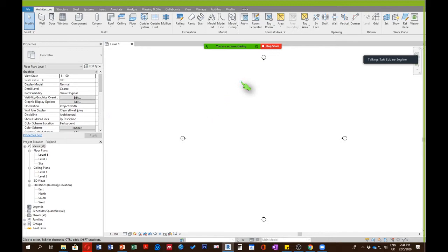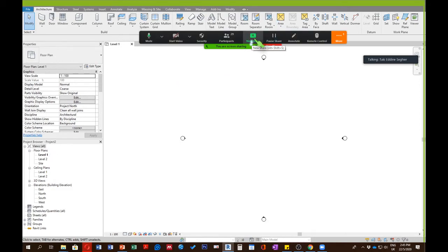Alright, so now we are doing the Revit preparation. We will not do the modeling, but I will just create these floors that I need and orientation and things that I talked about. So the first step I already did, I'm using now the template that I gave you. So I think this one is very clear. Next step, as you can see, the template has level 1 and level 2 in the floor plan. Please be careful here, floor plan, not ceiling plan, because I know some students sometimes go to ceiling plan.